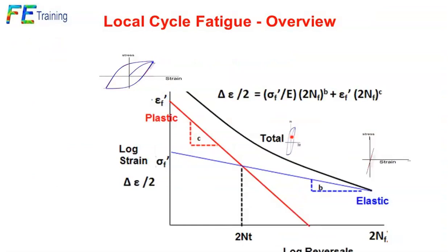So one of our jobs is to create these hysteresis loops. And what we're really interested in is not the nominal stress anymore. It's that stress range. Divide that by 2, gives us the stress amplitude. And that's what we're going to be using in this particular curve to look up the life. So if I've got a particular cycle, I can come in on a number of cycles. I can say there's, let's say, there's the strain range. There's my number of cycles to failure.